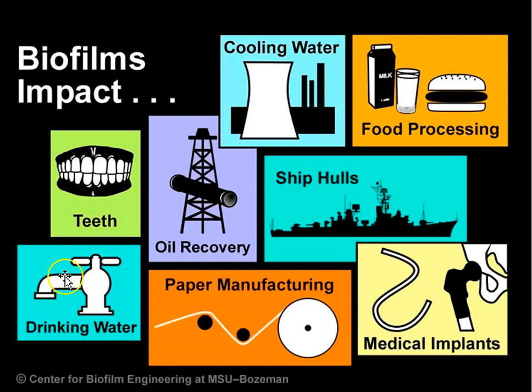And you've seen the plant, and one of the methods they use is UV radiation. So nice clean water irradiated by UV will pretty much kill everything. But it will not keep microorganisms from growing in the pipes downstream, because it only treats the water when it passes the UV radiation. So therefore they also add chlorine that follows the water. So that's an additional barrier at the same time as it is supposed to help avoid growth of biofilms inside the pipes.